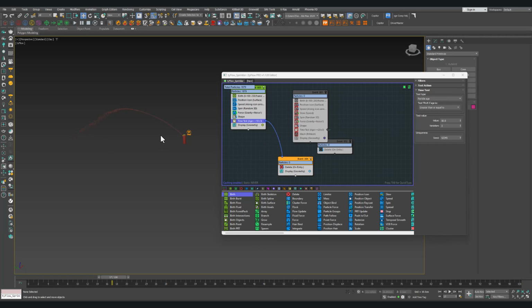That I'm gonna tell Tyflow to keep producing these particles in every frame until maybe 20 frames, with the age of particles with the variation of 3 frames, then go to this event and delete.